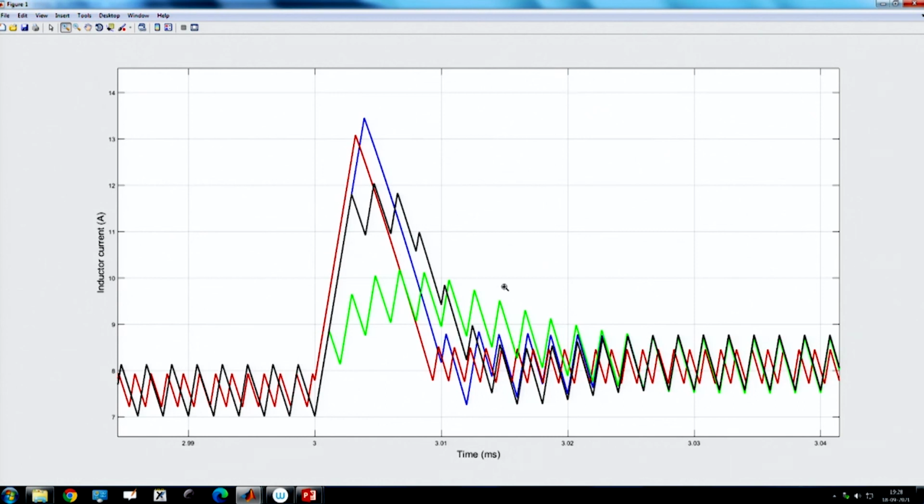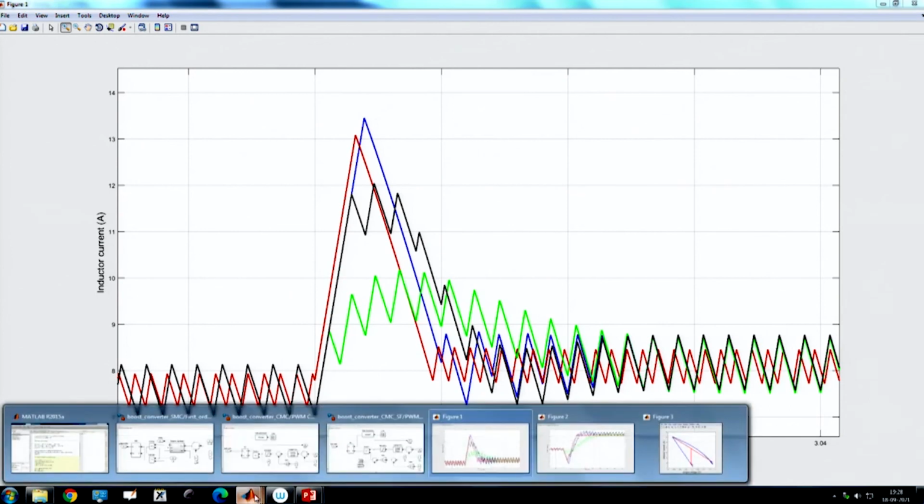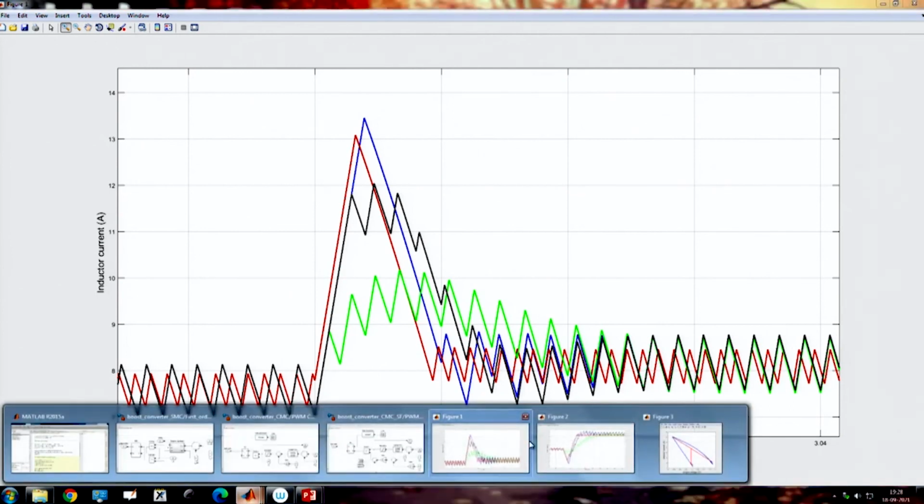the response is happening perfectly fine. This is the black color, but the linear model is invalid, and as per the linear model we have shown, whether it is current mode or voltage mode, from the loop transfer function equation at crossover frequency you cannot achieve crossover frequency above RHP0, because that was showing unstable. That is where the limitation of the linear controller is.